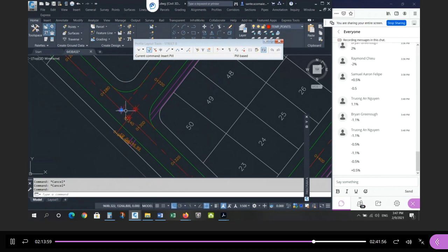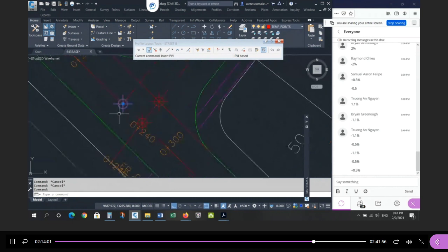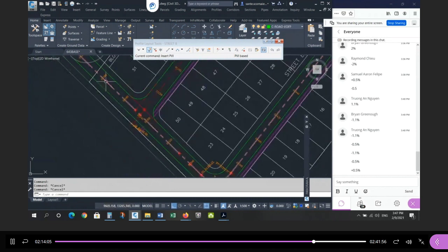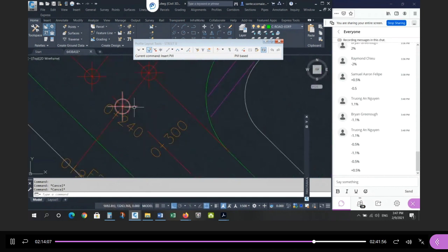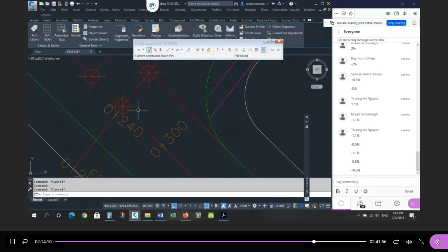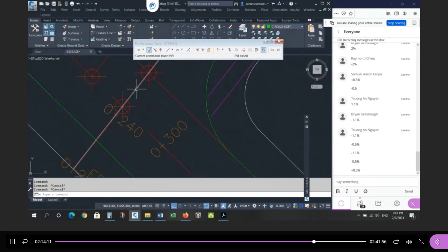So I need to project this so I can design that as a low point location, and then I need to interpolate this value, because when I'm done designing street B, I then need to take the elevation of this road profile at this location and project it to this location, this profile, right? This is a common elevation to both. So let's project these 2 points. Save my drawing before I lose it. So now I'm going to go to project the points. I want the low point and I want the intersection point.